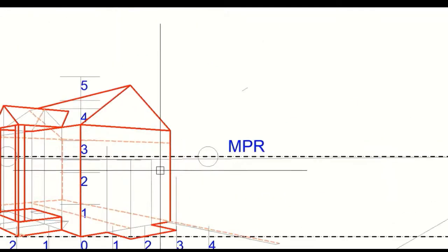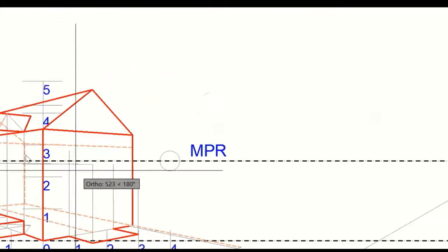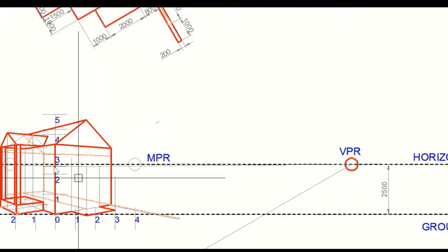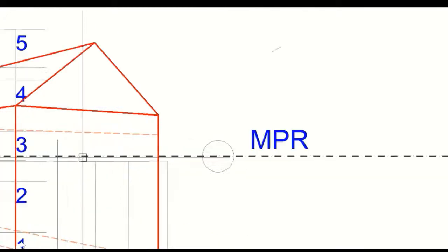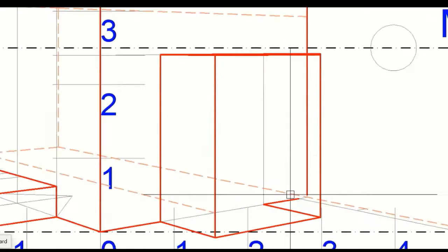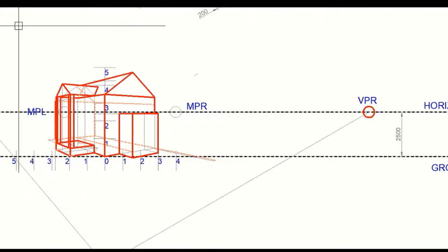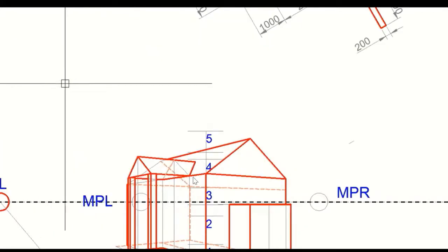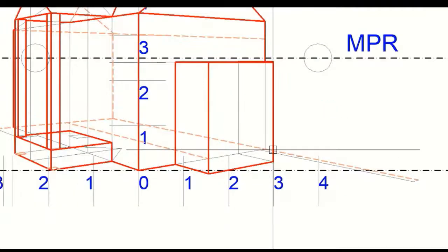We'll make this, it has a height of 2450 mm. So we have taken height from this point and drawn this. So it is always easier making perspective by any shortcut method if we draw the plan first using the grid, and then take the heights accordingly from the point wherever it touches the picture plane.